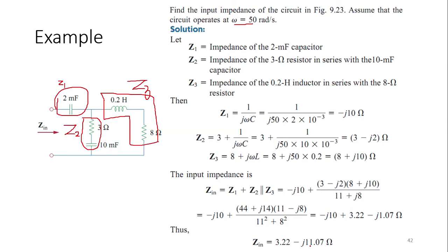So what can we conclude from this expression: is the overall circuit capacitive or inductive? From the real part we see that there is some impact of pure resistance. From the imaginary part, due to this sign, we can find out whether the net equivalent impedance is inductive or capacitive.